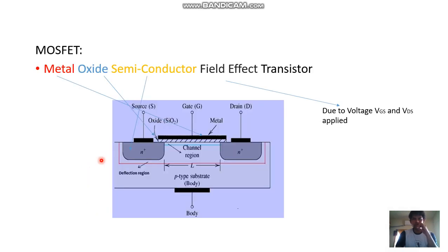We will discuss that. This is the metal oxide semiconductor field effect transistor. I hope you are already familiar with this. This is a metal layer, and this is the channel. For an N channel, we have two N regions and a P substrate. If it is a P channel, we have two P regions and an N substrate, and this is the channel, and it acts as a capacitor. This is one plate and this is another plate, and this is some dielectric region.